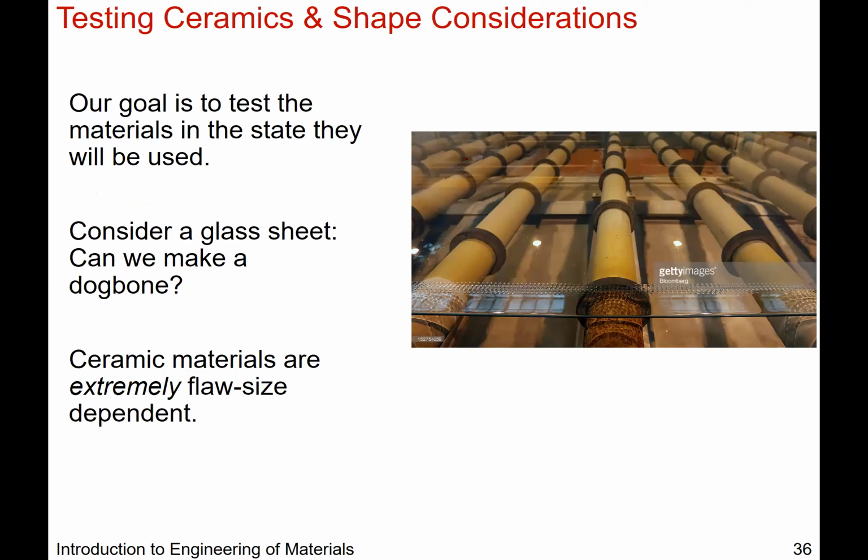Okay, so let's talk now about mechanical properties as opposed to the economics of alumina. Let's talk about how we can test. Let's say you have a single crystal sapphire, or you have ruby that somebody gave you. You can actually test the mechanical properties of these ceramics, but it's difficult to do so because the material will probably fracture before you get to meaningful numbers like we've gotten for metal systems.